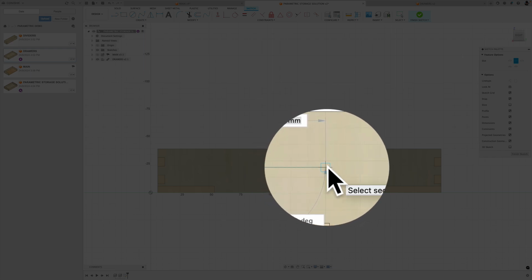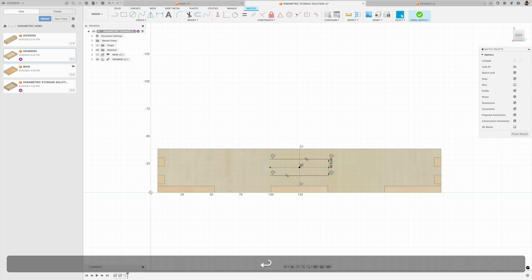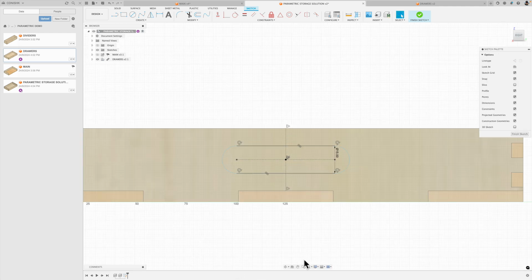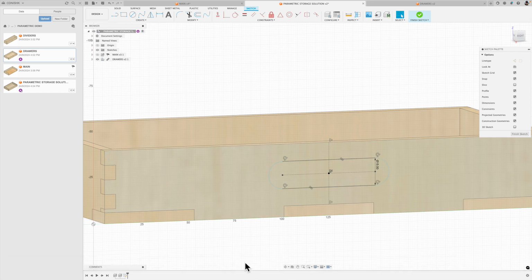So I'll pull out 1/2 of the slot, so 1/2 of its length. So I'm using, I think, 25 perhaps, and then we'll drag up to set the height. And then I think I'm using 15. Right, one thing to note here, you'll see that part of the sketch is black, defined with a measurement, and some part of it is blue. So you want to have your sketches fully defined. It means the blue part of the sketch is missing some form of measurement.